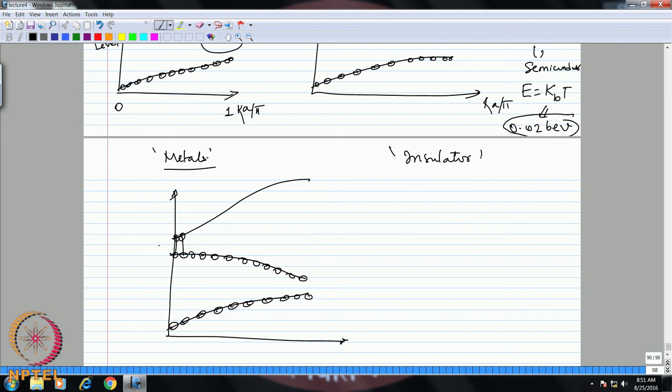On the conduction band you have 2 electrons, and now you introduce a donor. The Fermi energy of the donor is closer to the conduction band of this material. Therefore, at higher temperatures there is a chance of these electrons from the donor jumping to the conduction band of the host material,